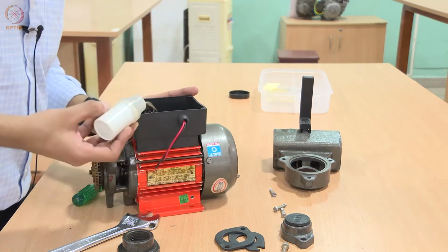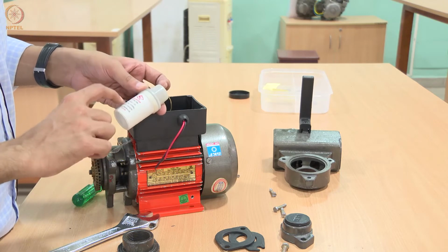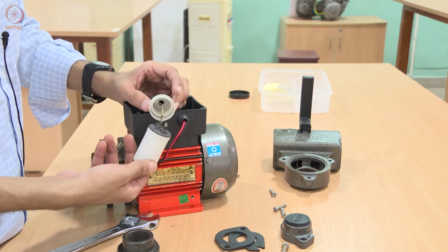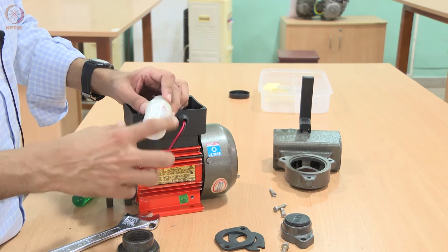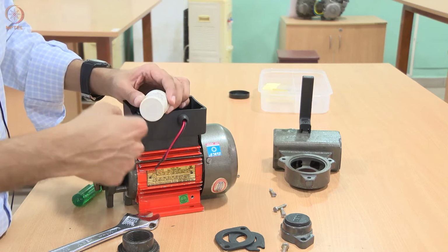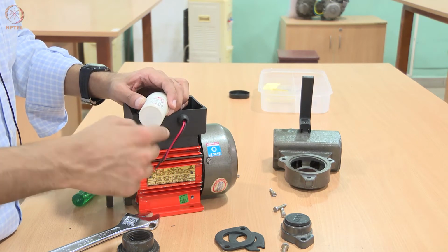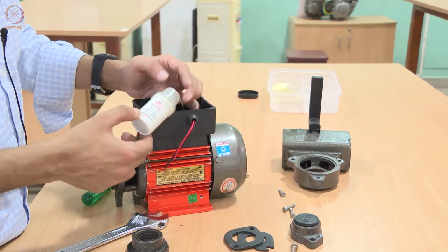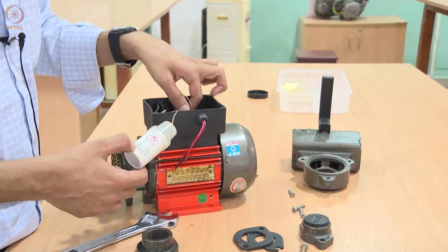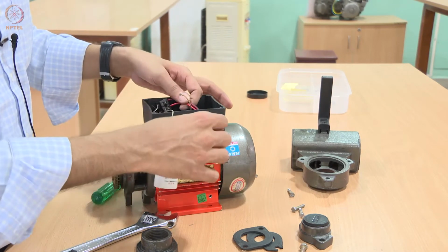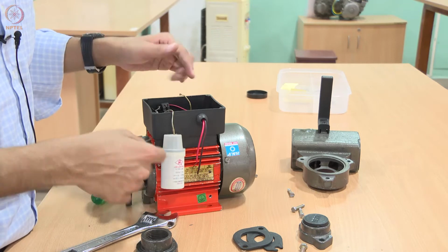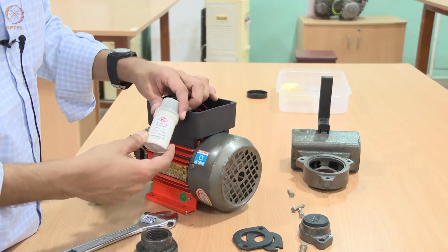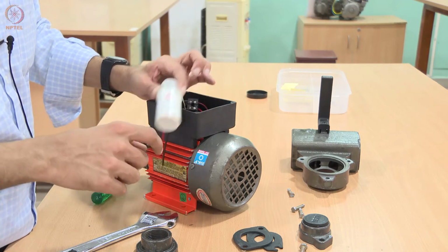Now you have a standard 10 microfarad electrolytic capacitor. These capacitors are called electrolytic. You can see it is filled with a coil of parallel plates in coil form, and there is a dielectric that fills it. This capacitor is connected to the starting winding, and the other line is connected to the running winding. So basically you have two windings. Occasionally, every 3 to 4 years, you may have to replace the capacitor as it gets old.